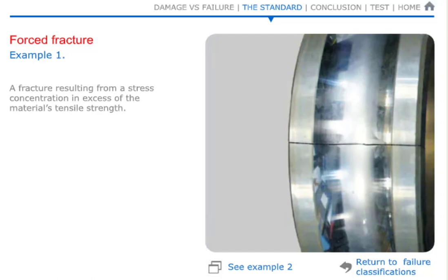Force fracture can also result from excessive drive-up on a tapered seat or sleeve. The resulting tensile stresses or hoop stresses arising in the rings produce cracks when the bearing is put into operation.